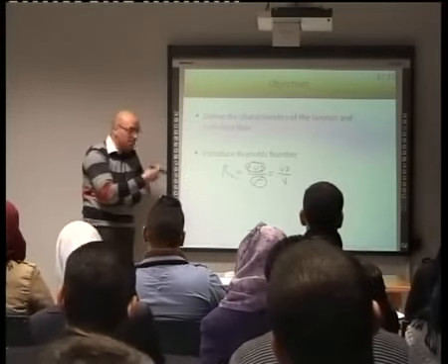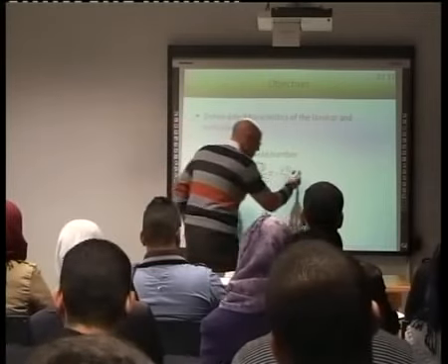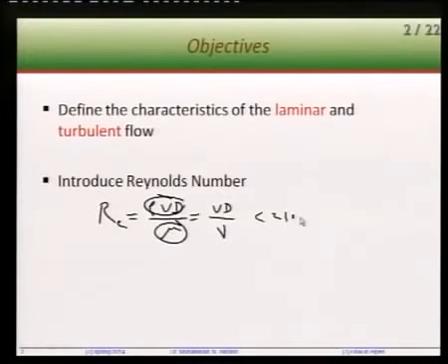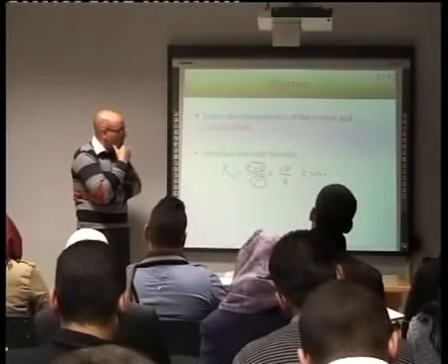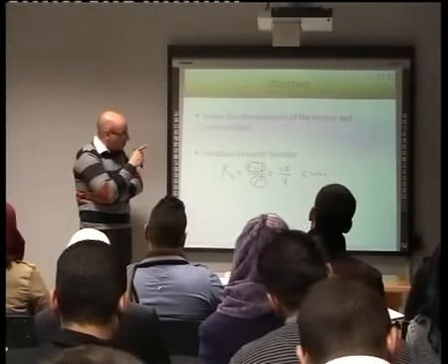So if Reynolds number is less than 2100, then this is laminar. That means the viscosity will suppress the flow and the flow will travel at a slow velocity. But if it is really larger than 2300 or something like that, then that will be a different value in the end.